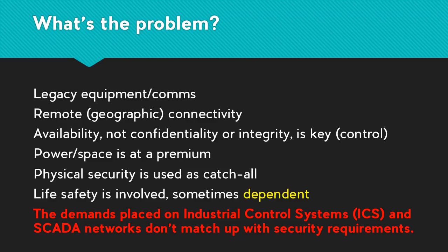So a lot of that depends upon the safety PLCs, the safety equipment being accessible at all times, being able to connect to all of the remote sensors, the sniffers to look for toxic gas concentrations, things like that. If you have an OT incident that affects the availability of your HSE controllers, or your safety instrumented systems, SIS, then you've got a serious problem. You've actually got life safety concerns riding upon that Ethernet connection if that's how they're connected.